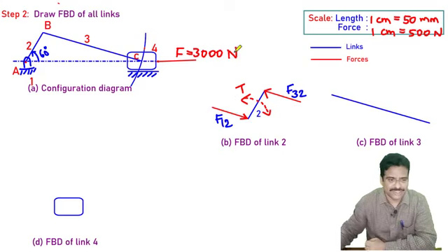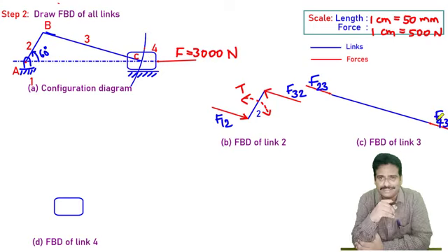Link 3, as you could see, is a 2 force member. So I will have a constrained force here. I will draw one constrained force parallel to link 3. Similarly, at this end, I will draw a constrained force. So what is this name? This is the force exerted by link 2 on 3. This side, link 4 exerts force on link 3. So we could say link 3, that means the connecting rod link, is a 2 force member.